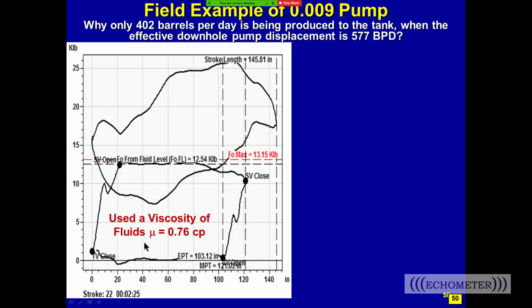So this is the well, and the tubing is anchored, and this shape that looks like this on the sides, it's anchored, it's not unanchored. Why do I know? Because I told the operator it might be unanchored. He went out and checked it, and no, it's anchored, he said. And we were using a default; we weren't using any slippage calculator at all. And he said, "What's wrong?"